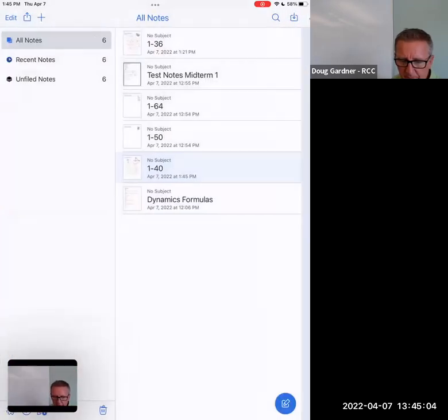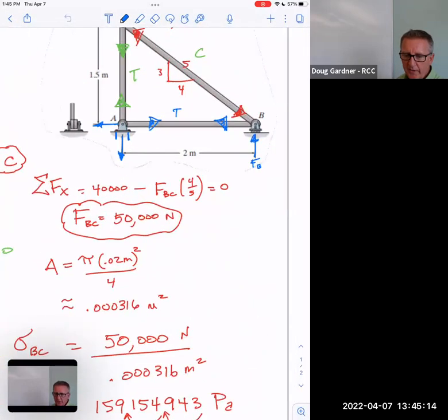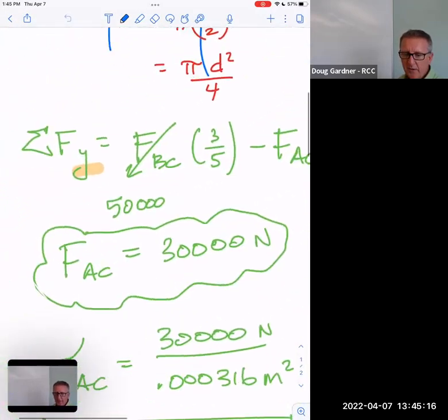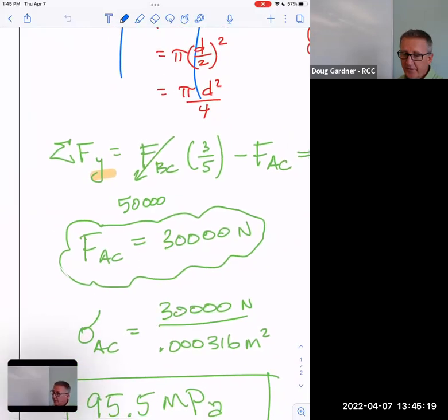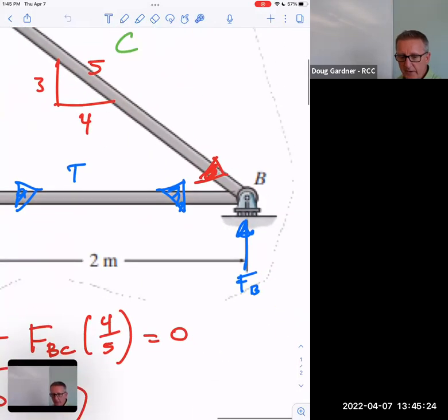All right, how's your brain? So if you gave us the AB, are you saying what you would have had to do is do the moment around A and get that Y? Well, we just have to do this one more, like this calculation we just did over here to convert 50,000 to 30,000. We'd just be doing the same thing over here. We know that this force right here is 50,000. So 4/5 of 50,000 are trying to get it to go this way. 4/5 of 50,000 is 40,000. So this would be 40,000 divided by our area, and that's where 127 came from.